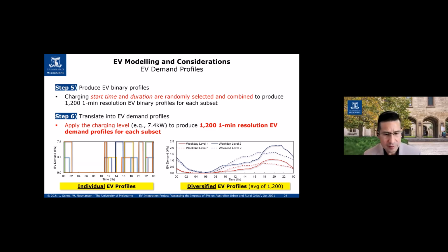Yes. So one thing that is very important is that we haven't used the cyclic ratings of transformers or conductors. So we have just used the normal ratings of the corresponding season of the peak days, so the summer rating or the winter rating. But transformers have cyclic ratings as well that they can withstand easily, 10 or 20%, depending on what each DNSP uses. So we tried not to use that just to demonstrate the extent of the effects. But definitely, that's something that eventually the decision makers within DNSPs need to consider. So yes, that's a good point to raise.